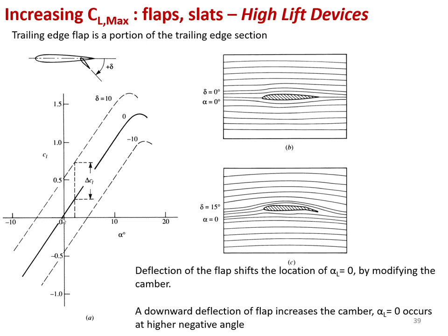Move it from close to zero to negative for positive values of angle, and from close to zero to positive for the negative camber that you have created in your system. Okay. There's also another small change that is happening, that is the location, the angle of attack at which the stall happens, that also moves with zero lift angle of attack.